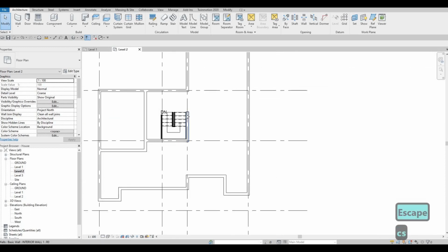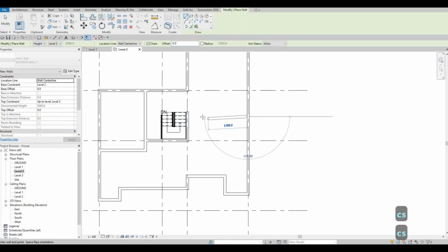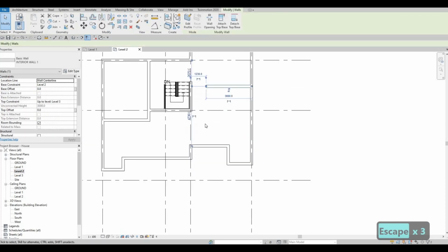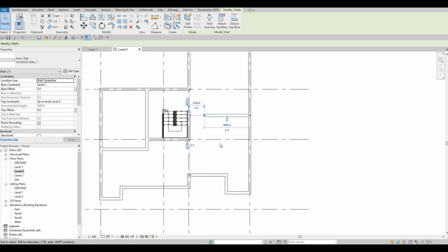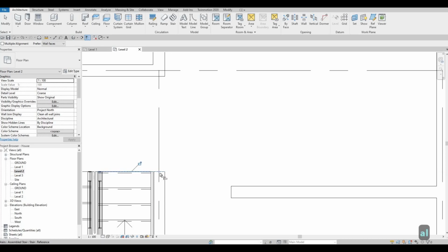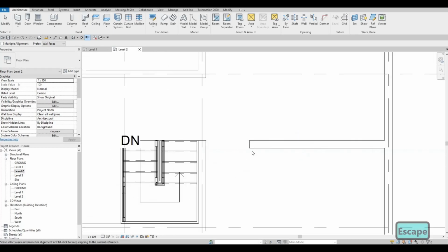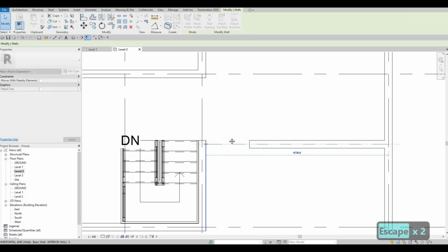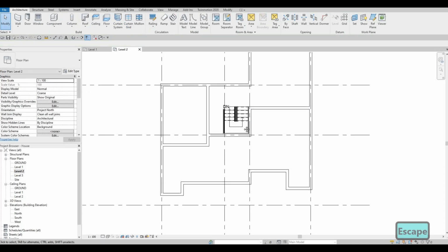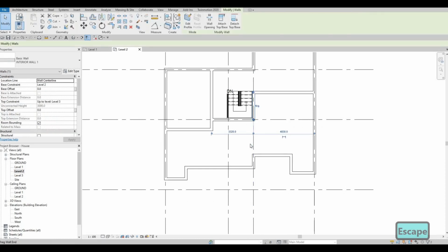and then after that you could just align this, or we could add in the same wall, interior wall. Select that, and you want to check it, and it's better to have it link right here. So I'm gonna AL, and then let's align this, and then now align this again to this face. So everything is aligned. We can then join them all together, and as you can see, that looks nice. And then again, we're going to extend this wall all the way here. So we're just gonna grab this and extend this all the way there.